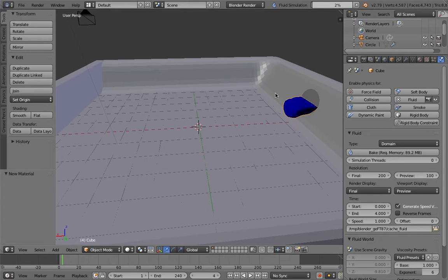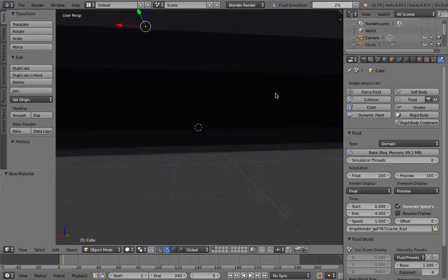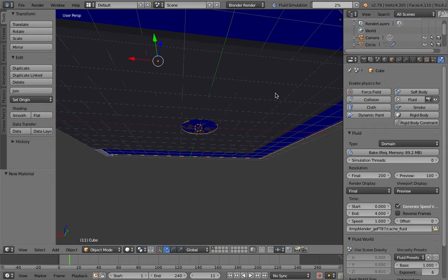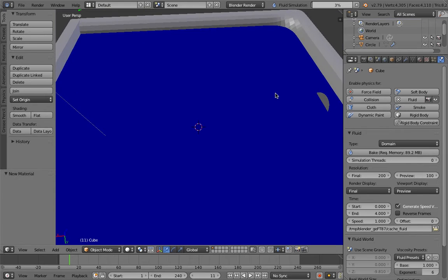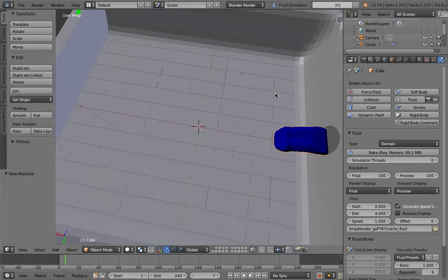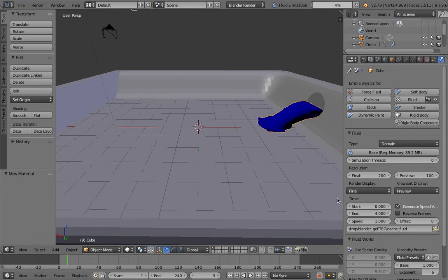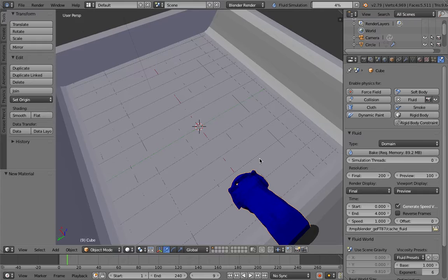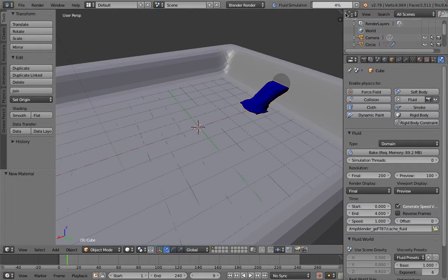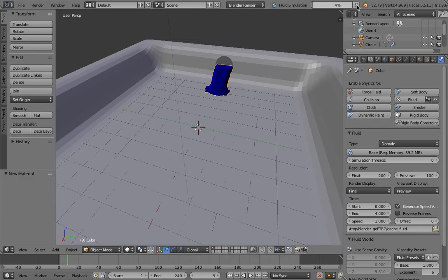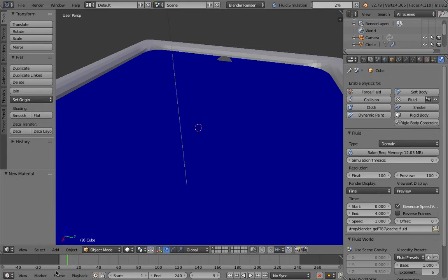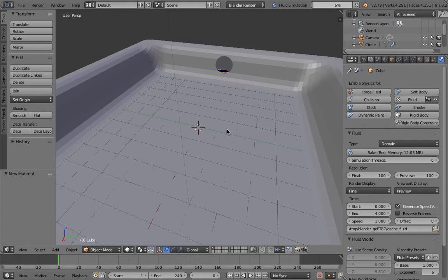We'll be essentially getting the actual fluid simulation. So what you should see in here is that it splashes a bit. Before you bake it, you can switch these settings down a bit, of course. Because my computer isn't letting me, we have to cancel this and set this down to 100 as well. I'm sorry about this. And now bake it. What you should see is it goes much faster.